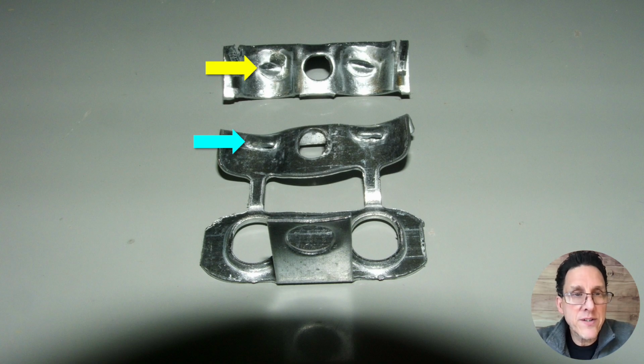And if you notice that bottom clamp, that metal bump there, that has a kind of a sharp edge. You would not want to tighten that clamp down on an NM cable or a UF cable, because you'd probably damage that cable jacket and potentially short out the cable or ground it out because it's too sharp of an edge. It needs to be a more rounded or a smooth edge.